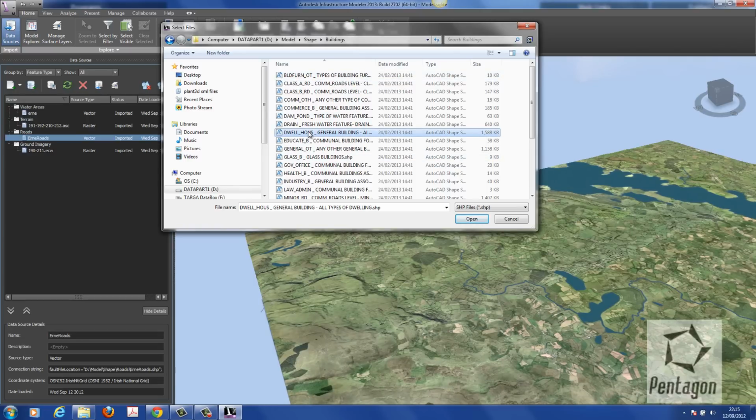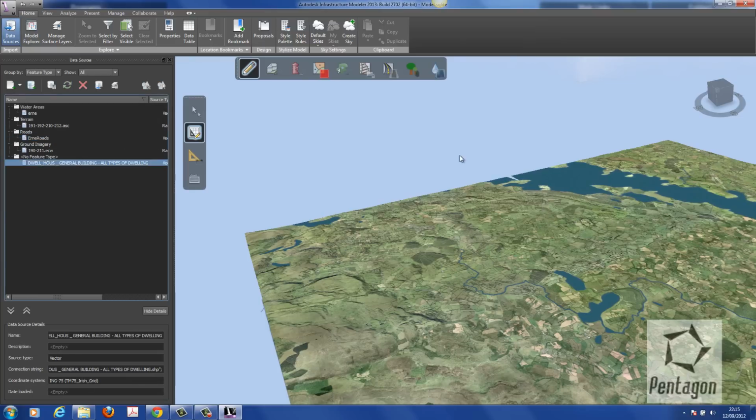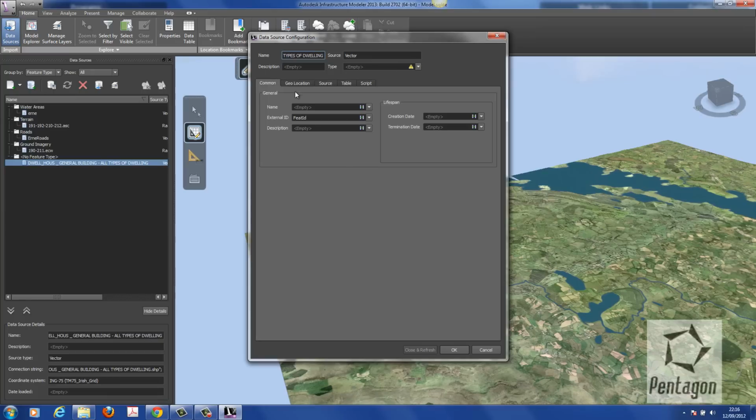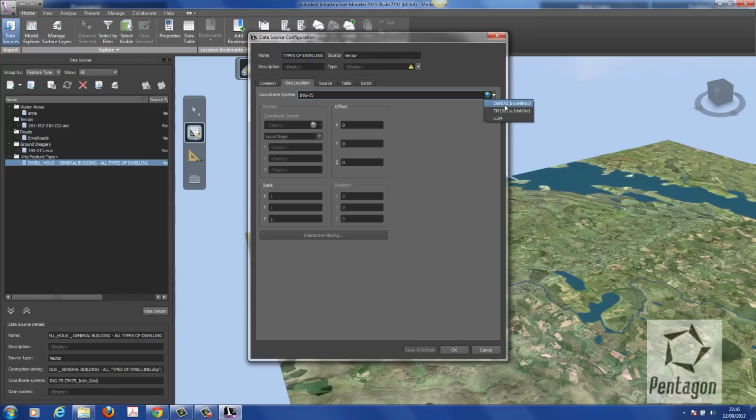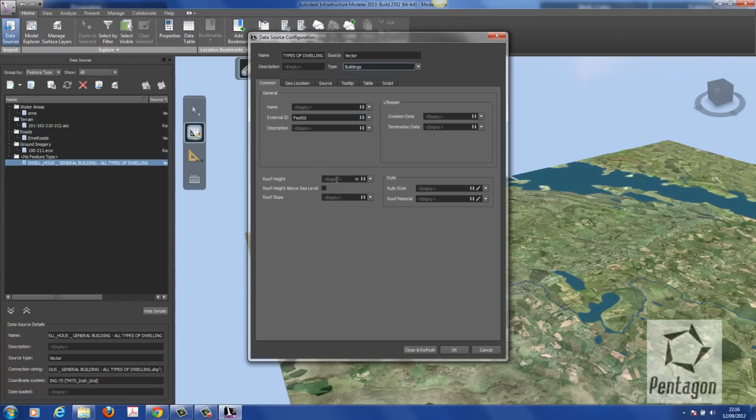And it depends on the Ordnance Survey data that you're actually using. You could use some shape information that actually has a classification for the height of the house. In this case, I don't actually have it, so we're just going to say, look, geolocation. We're going to make sure it's Irish grid. We're going to classify it as a building. If we did want to put a common height in here, we would do it in here. We could add that in as a table if there was a feature code we actually knew to read it off from. In this case I don't, so I'm going to have to put a generic height as 10 in.